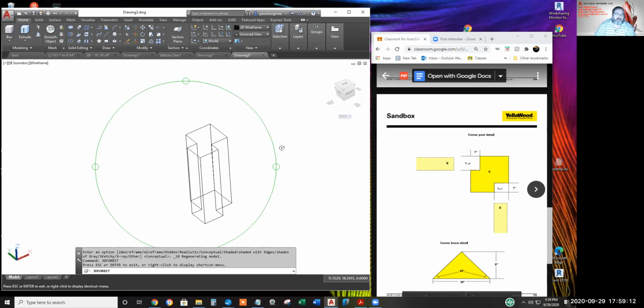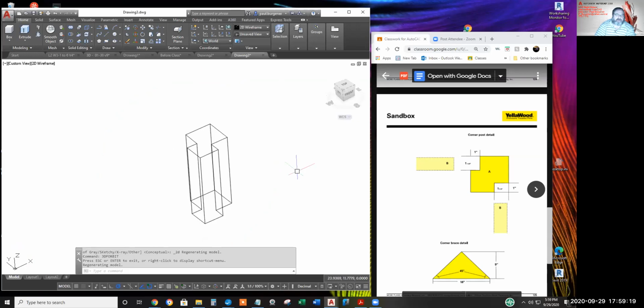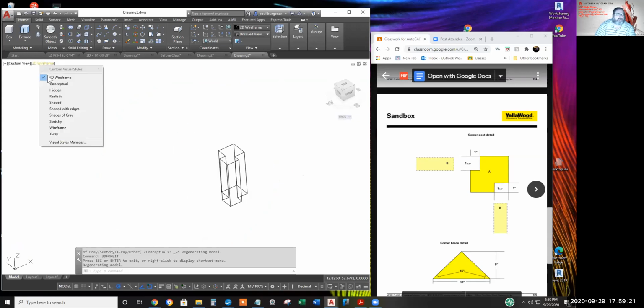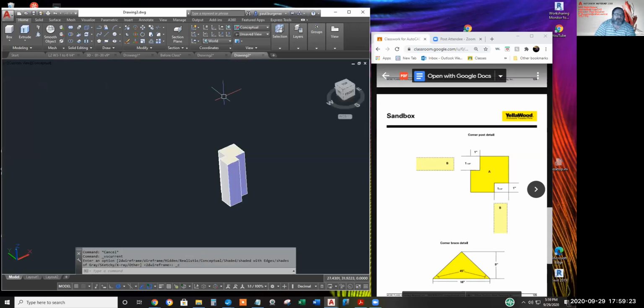Again, tweak it a hair so your Z-axis doesn't line up with a 45-degree increment. Hit enter to bail out. Spray paint it to get the warm and fuzzy. My 3D viewing toolbar hasn't come back yet. Anyway, we need 4 of these. If we make one of each piece, we can cleverly mirror one side of the sandbox to form the other 3.